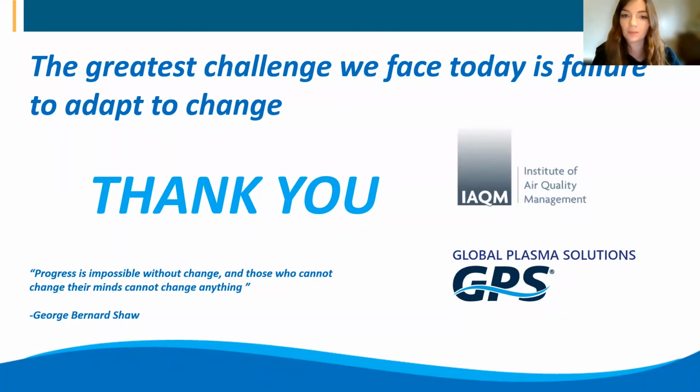Thank you. And kind of related to that point, we've got two questions asking how filters are disposed of effectively to prevent the re-release of filtered particles, especially when they've been used to target things like airborne viruses. Sure. So I'm not an expert on filter maintenance, but I can tell you what ASHRAE here in the United States says. There's a couple things you can do. Number one, wear PPE when you're doing a filter change. We always should have been wearing PPE, right? It's just come to the forefront with SARS-CoV-2. A filter maintenance person should probably be wearing gloves. They should probably be wearing goggles. They should probably be wearing an N95 or equivalent mask, perhaps more, right?